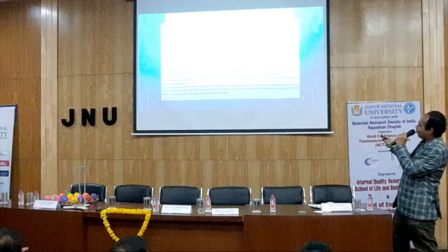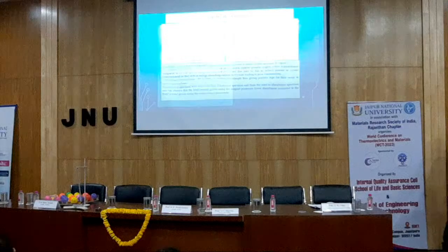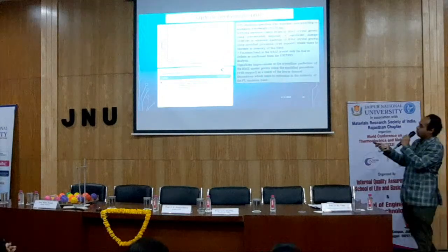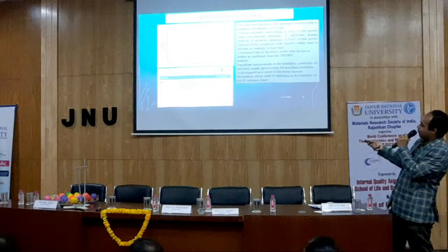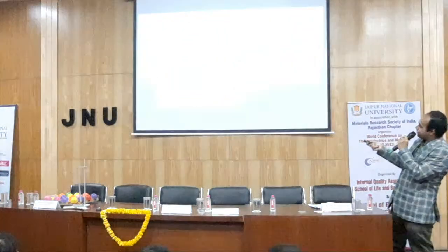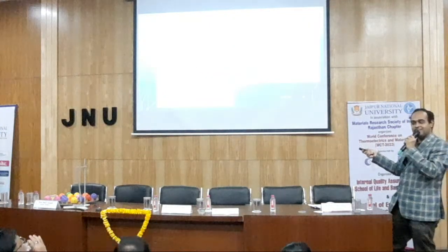And this was the optical, and this was also confirmed by photoluminescence. The defect density was drastically reduced. If you see, the photoluminescence of this has a peak due to defects. But when you go for the modified procedure, the intensity was very much reduced, indicating fewer defects, and it was confirmed through the high resolution X-ray diffractometer.